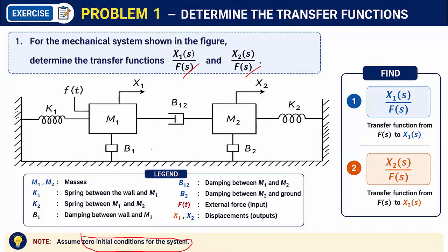While we are writing the differential equations, we need to consider nodes, because based on the elements that are connected to the nodes, we are going to write the differential equations. So we are considering mass elements as the nodes. In this problem we have two masses m1 and m2, so we have two nodes, 1 and 2.